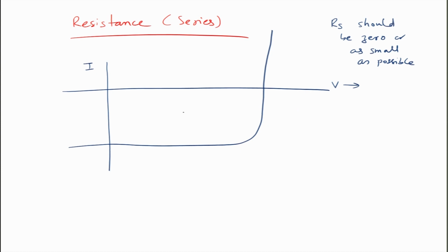So, the slope of this plot, of course, you can see you have 2 points. This point gives you a slope di by dv. The inverse of this is the resistance R1. Again at this point, which is at VOC, di by dv inverse is equal to R2 at ISC.